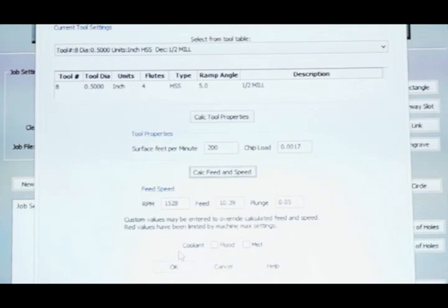So you can either accept the one from your tool and material choice, or you can enter your own. You can go back now and say, I don't believe in any of that stuff, I want the feed rate to be something. You can go in and enter a feed rate now, and I'll carry it through the program and use it. You don't have to use my calculations of it. That's a helpful side thing, yes.